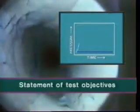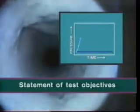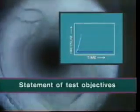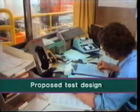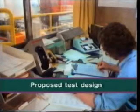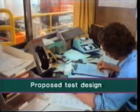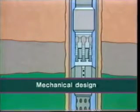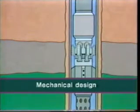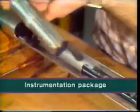A statement of test objectives, including why the well is being tested and what we expect to learn from the test data. A proposed test design, including the specification of the type of test to be run, flow rates, shut-in periods, durations, and contingency procedures in the event that the test has to be altered in the field. The mechanical design should specify the required surface and subsurface mechanical system. The instrumentation package must also be specified.